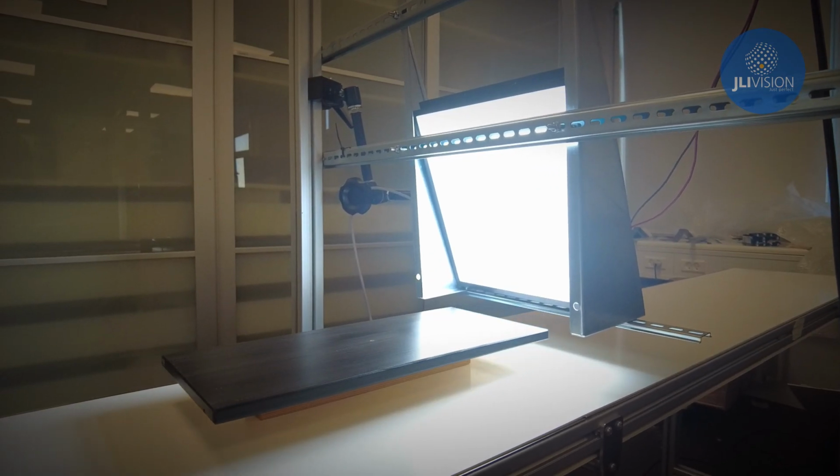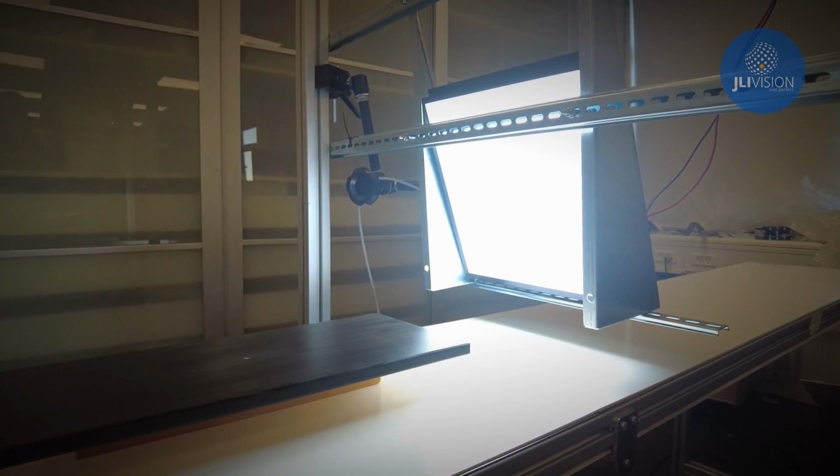Another challenge we also have is, let's say we have a different type of product. We have something that's white and we have something that's black. It's clear that these two objects will require different lighting. This is also something we can adjust in our products by changing it from within the system. So let's say we have a dark object, we will then turn up the brightness of the light to actually see the defects that we want to see. Whereas on a white product, if we had the same brightness, we would not be able to see anything. Therefore, for a white surface or product, we will have to turn down the brightness to actually see the details we need to see.